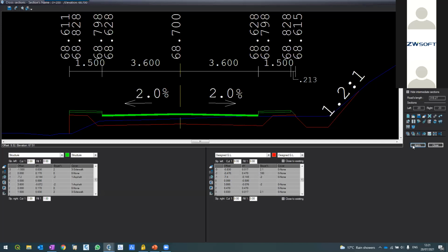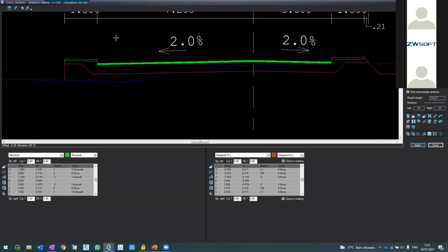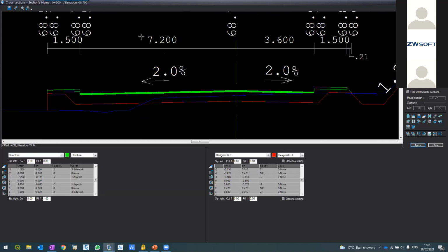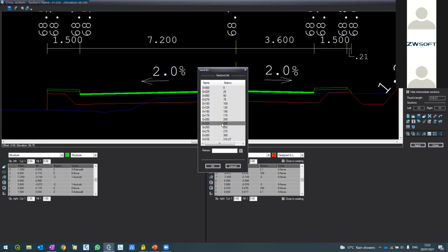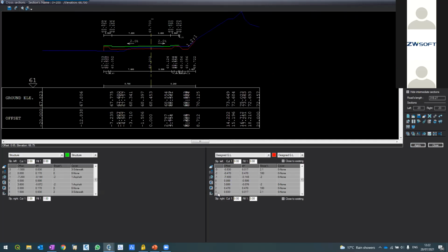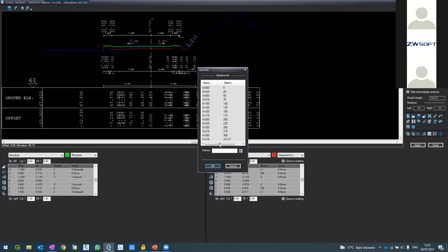See what I've done? I've extended this one. So this is a new template which applies only from 200. In fact, I had to tell the software, project this to all the sections from 200 and up. Project the change which I did from 200 and up.